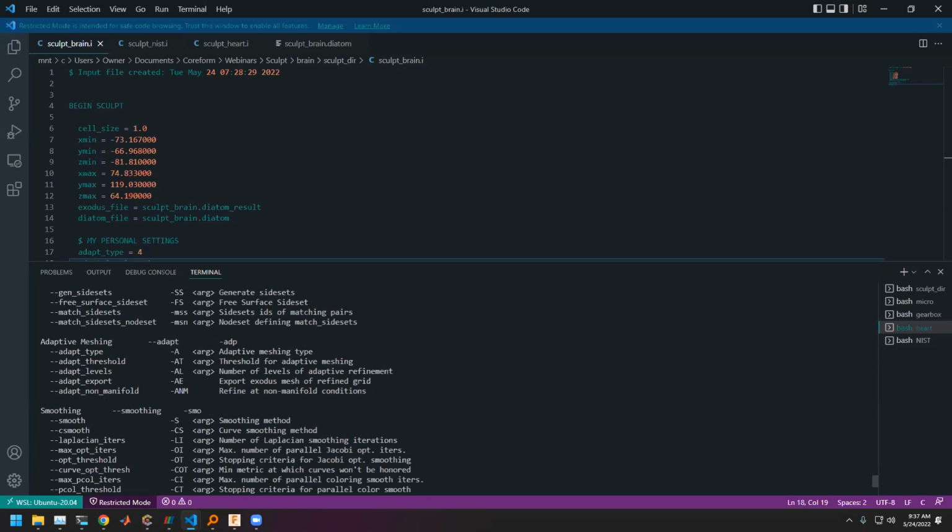Cubit is really a meshing and finite element meshing tool, and the stuff of extracting surfaces and smoothing them and healing STL files, those are things that aren't in Cubit's wheelhouse. And so I do recommend using tools like MeshLab, Meshmixer.